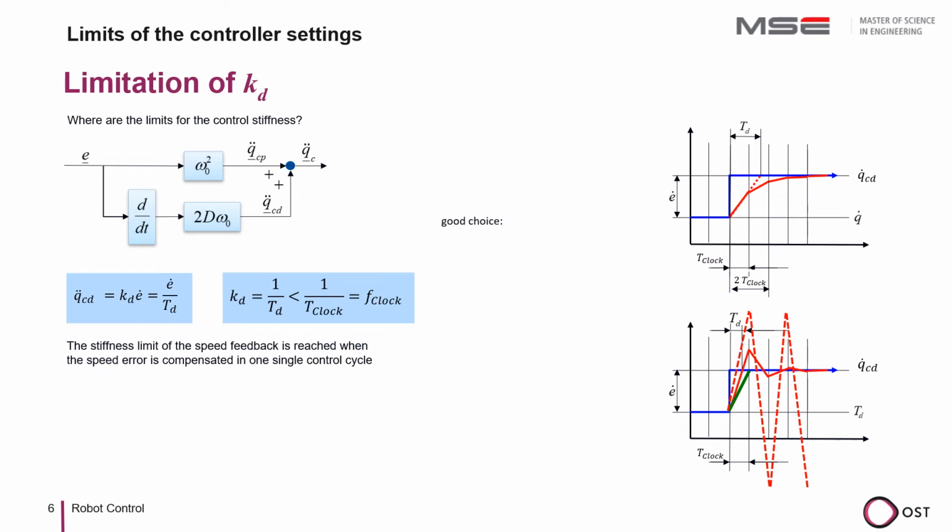The algorithms need time to be calculated, and often the inputs and outputs are triggered almost simultaneously to have a common time pace. This leads to a time delay of up to 1 control cycle. Further time delays are caused, for example, by the numerical differentiation of the position signal. It therefore makes sense to start from twice the value of the control cycle and to add a small safety factor.